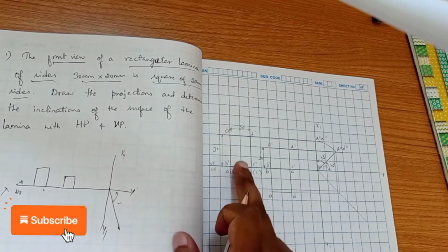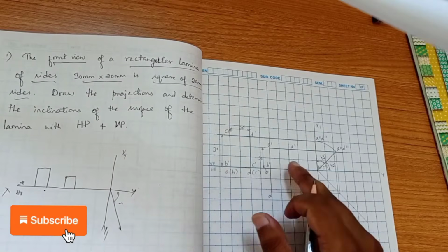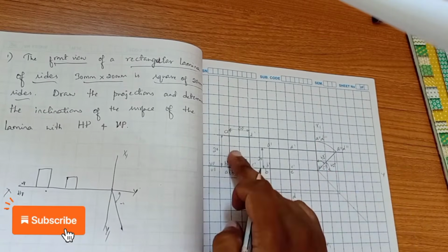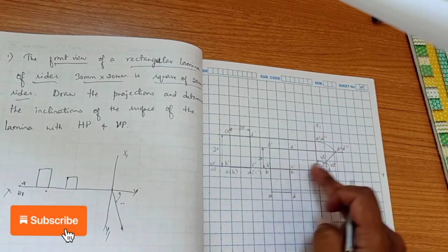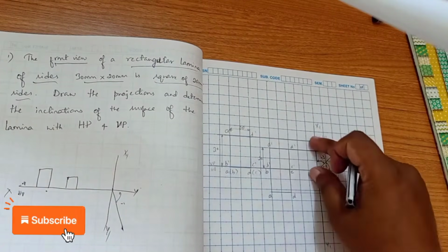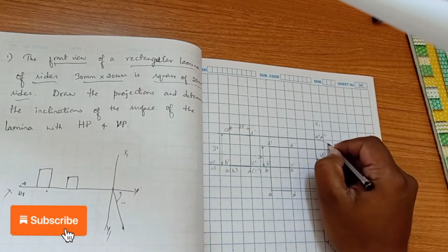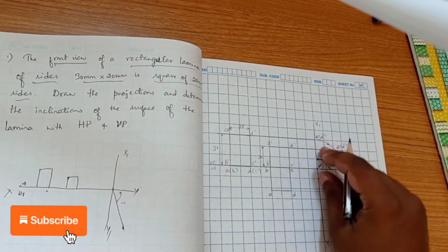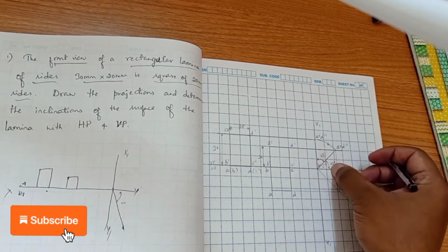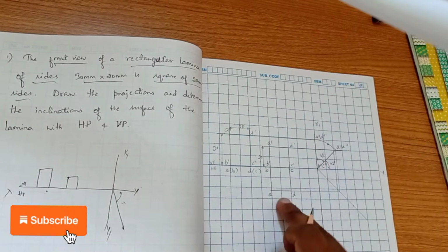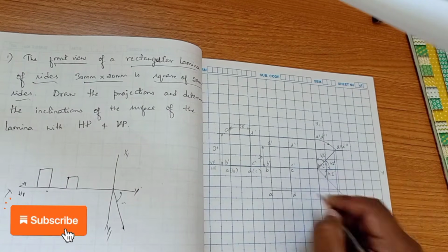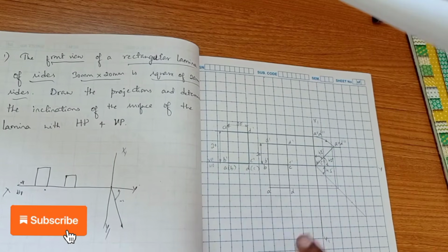So in this position, first we have drawn this one and the top view. Second, after that we have drawn this one. Then after that we have drawn an x1 y1 line to draw the side views. The side view of this is falling on the xy line, and the side view of this is falling here, because we are inclining this in such a manner that we get the top view. So we are inclining it by means of an arc here, showing the direction with the arrow mark. By cutting the arc, we get the side view of this position. By doing this, we get both angles, the angle of inclination to HP and the angle of inclination to VP. Then the top view of this position we get by drawing a 45-degree angle line.